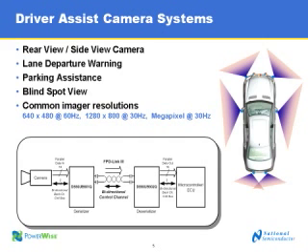And if you want to talk just quickly to the diagram. Sure thing. So if we look on the right of the diagram, we have the microcontroller, the ECU, controlling all the information and the processing that's done. From there, we have a deserializer, which is going to accept the data coming from the camera. So we have the camera on the left sending video data to the deserializer, as well as communicating I2C.